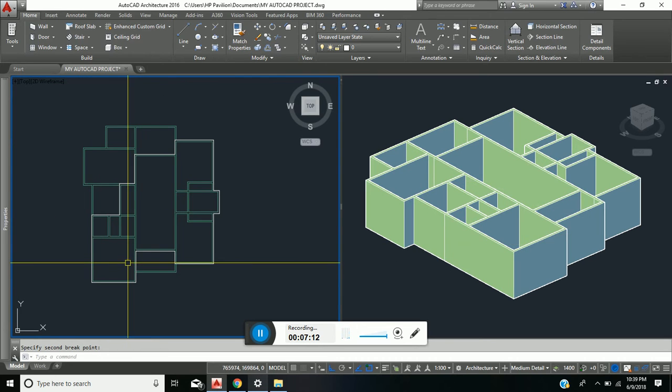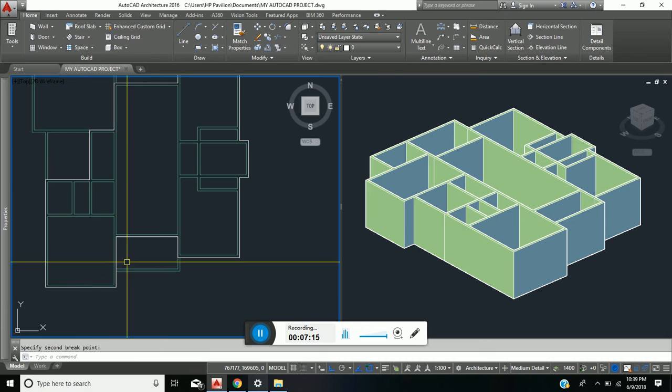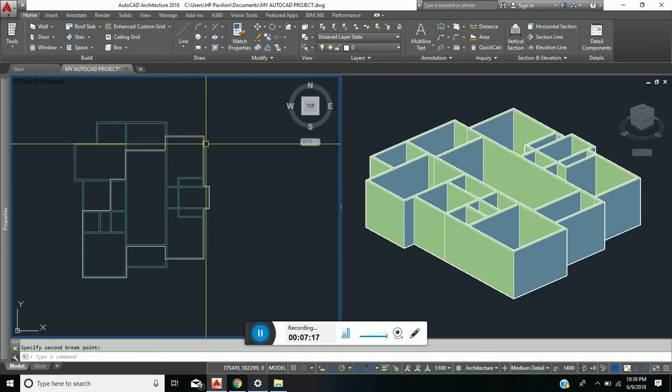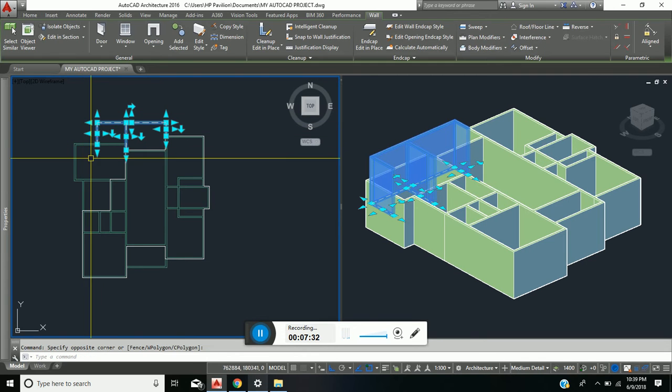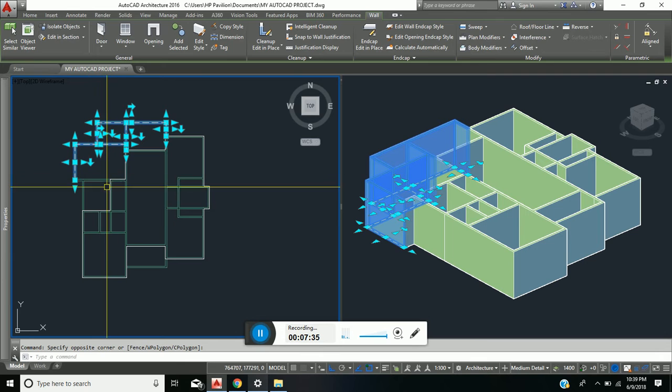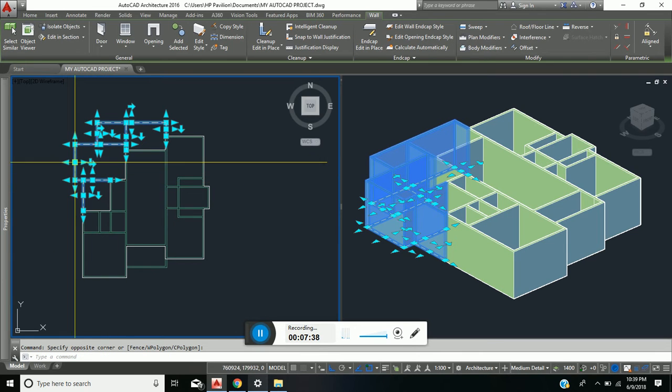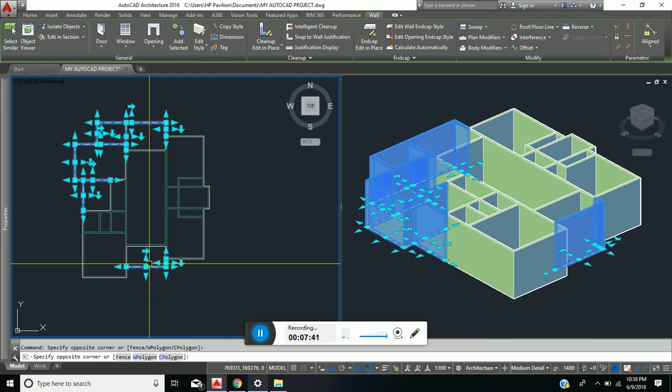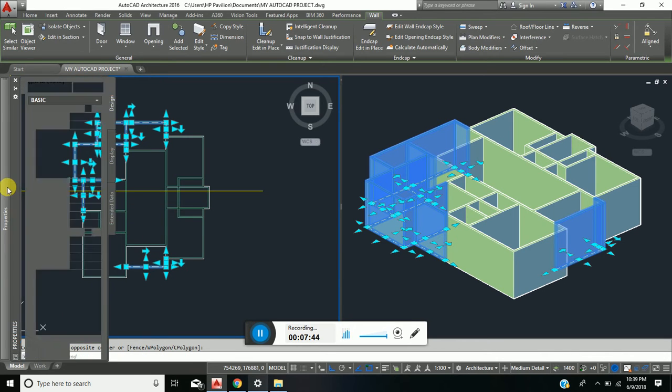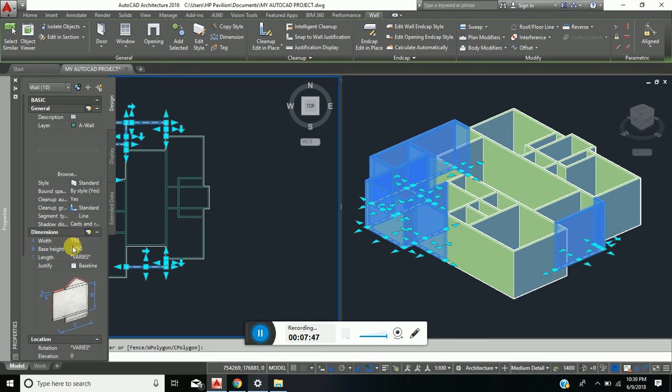Now I'm going to be reducing all the other walls, or all walls external to that perimeter line, because those walls would be reduced to a height of 2,700 to accommodate the slab portion of the wall. So let me go ahead and select all of these walls, those two, and these two lines. From my properties, I'm going to change the height from 3,450 to 2,700.